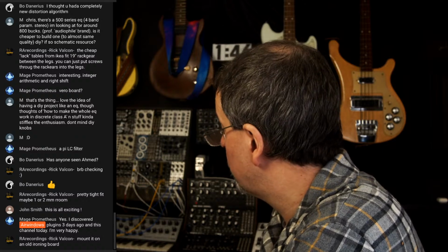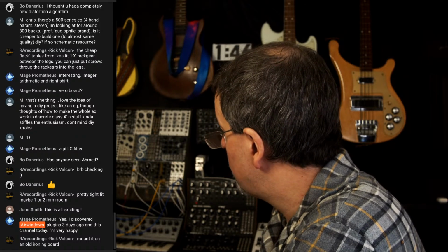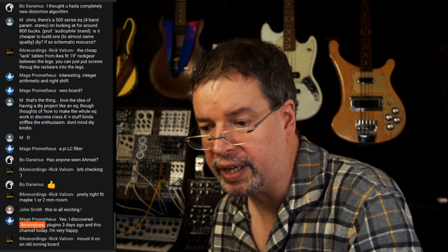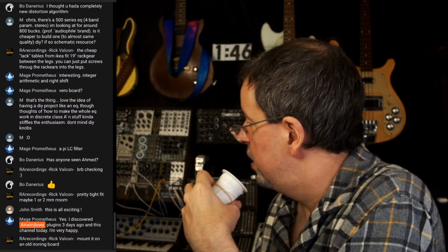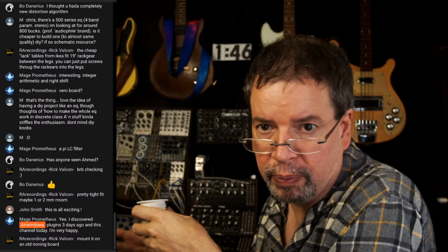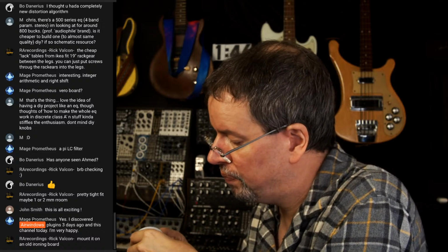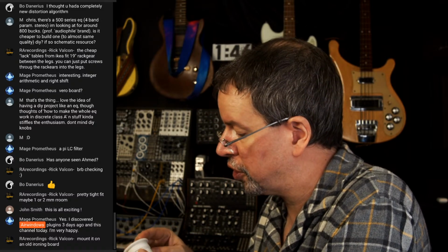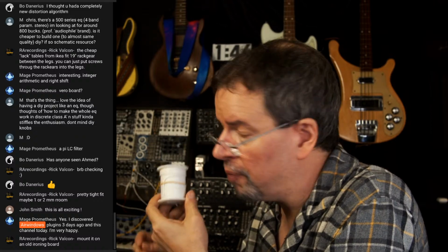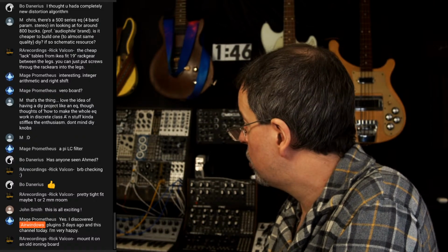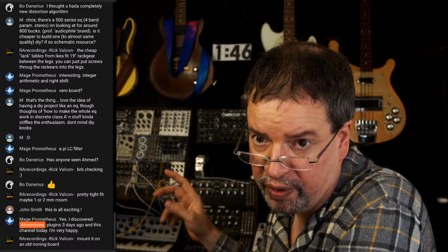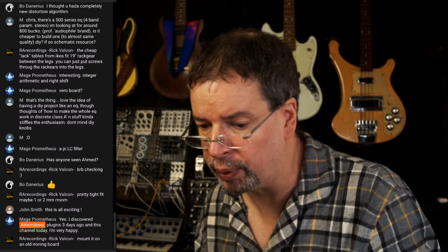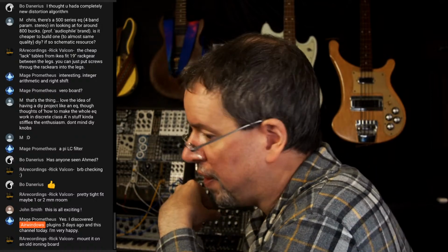But I'm thinking of doing it over again or just updating it so that my control wires are white wires, much like this. And that becomes just, these are trigger pulses, these are timing, this is control circuitry, typically digital control circuitry, and that's what the white wire means. But if I'm running audio, that could be like red or blue or something like that. And I can color code that with the full range of colors available so that that tells a story as well.